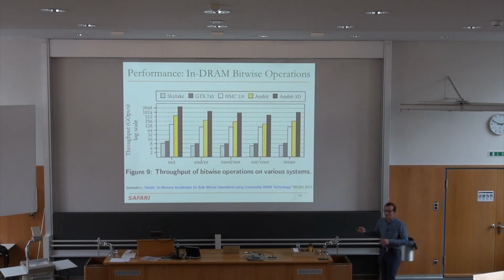We're designing these GPUs that can do a lot more computation internally. In DRAM, we're still doing computation. Basically, you need to put the substrate such that you can power up the chip and also cool down the chip. Clearly, if you put computation inside a memory chip, you don't expect power to remain the same. So you need to create the infrastructure to ensure that you can sustain that power as well as the cooling mechanism. But that's easy, I think. We know how to do that from the CPUs.